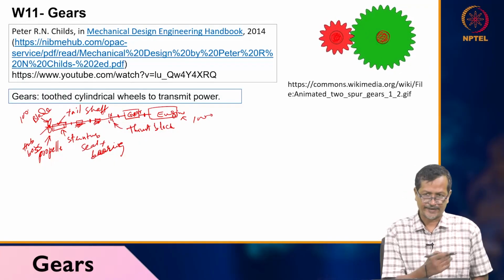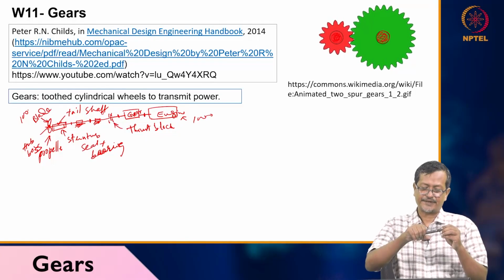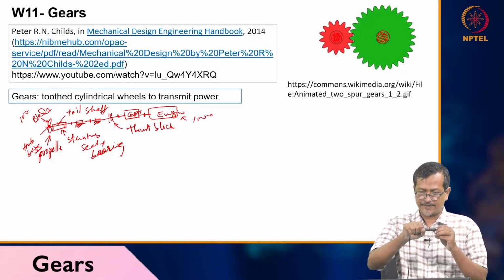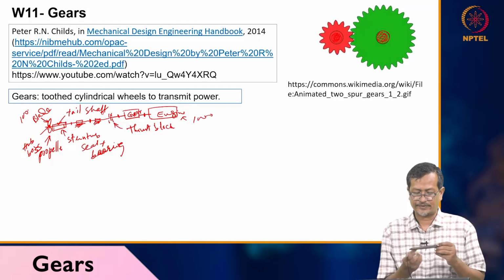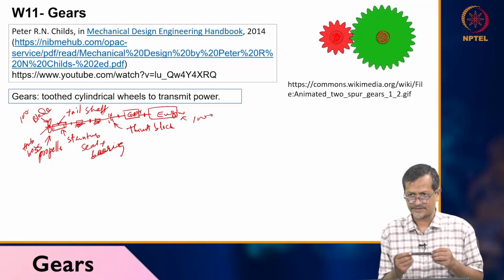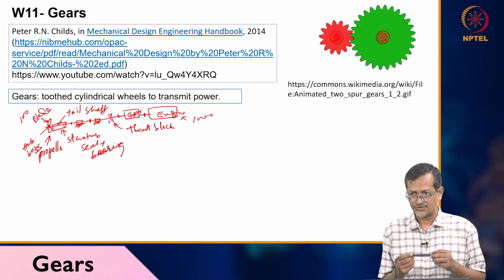So the propeller will be hanging; actually it will be creating a cantilever. When it is creating a cantilever, that means it should be passing through certain bearing. Normally it will be a sleeve bearing or muff bearing or journal type bearing. Ball bearing will not work, because whenever heavy load and very high speed are there, in that case we do not use ball bearing or roller bearing. We use journal type bearing.